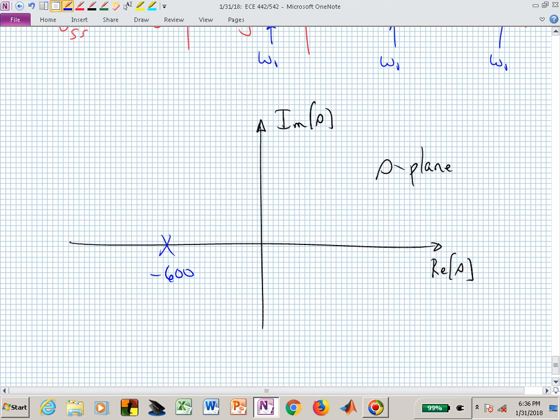Now what? Well, if you remember talking about the circus tent, we have an infinite pole sticking out at that pole location, and we have a rubber sheet stretched on top of it. Now to find the frequency response, we start at DC, which is the origin, and we just walk up that imaginary axis. We're evaluating that system at j omega for each omega. So we just take little steps along this imaginary axis, and we can evaluate the system's frequency response at each frequency omega. And which frequency are we interested in? The input frequency, omega 1. So we now need to walk up here an amount consistent with j500.